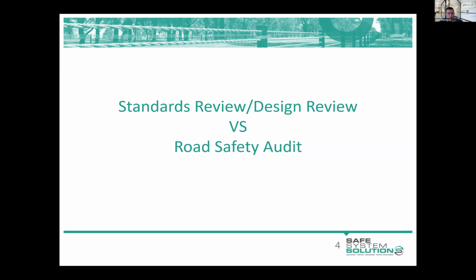As an auditor, really put that safety hat on, try and put standards to the side, put yourself in the position of the road users that would be expected to use the piece of road and interact with all the different design features, and really think about, is there a safety issue?